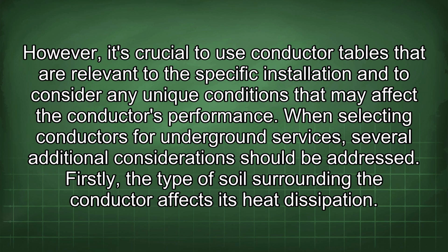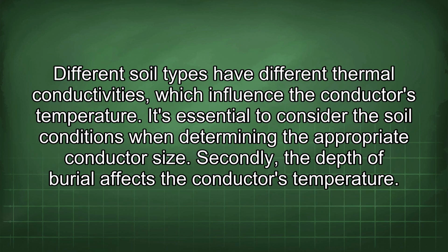When selecting conductors for underground services, several additional considerations should be addressed. Firstly, the type of soil surrounding the conductor affects its heat dissipation. Different soil types have different thermal conductivities, which influence the conductor's temperature. It's essential to consider the soil conditions when determining the appropriate conductor size.